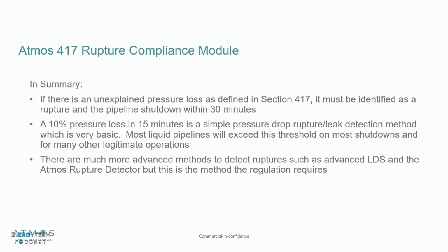And it says you must have leak detection to detect ruptures, and you must shut down within 30 minutes if you think you have a rupture. Now, I think that's a great idea. If you think you have a rupture, you should shut down maybe a bit quicker than 30 minutes. But what they have prescribed, firstly, is that a rupture is a 10% pressure drop in 15 minutes. So what they are doing with that is prescribing that you use the simple pressure drop method for leak detection. And they have defined what a rupture is.